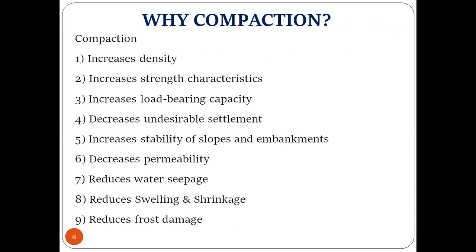And why is compaction needed? Compaction increases the density. As I told, when you apply the load and increase the water content, density increases. So to get denser soil, we require compaction, right? And it increases the strength characteristics. When the soil is very dense, we can say it is a stronger one, right? So strength characteristics also increase, and when it is a stronger one, it can bear the load. So it increases the load bearing capacity and decreases undesirable settlement.